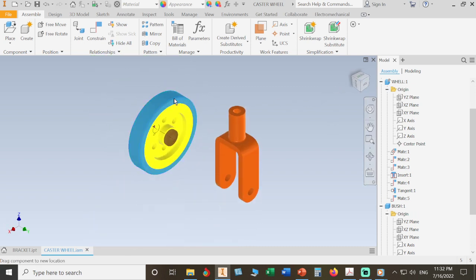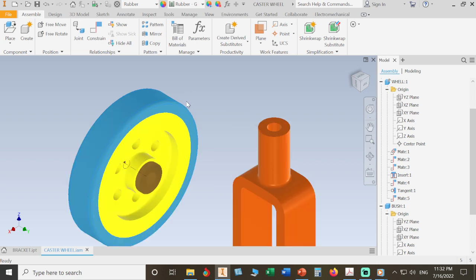Now our rubber is constrained or assembled to our wheel. Still rotate. Can you see one rotation degree of freedom here? Let us prevent it, because when our rubber rotates with our wheel, while our rotation, it will rotate together. Again, we'll add the fit tolerance to this one in order to prevent it from moving while it's working.